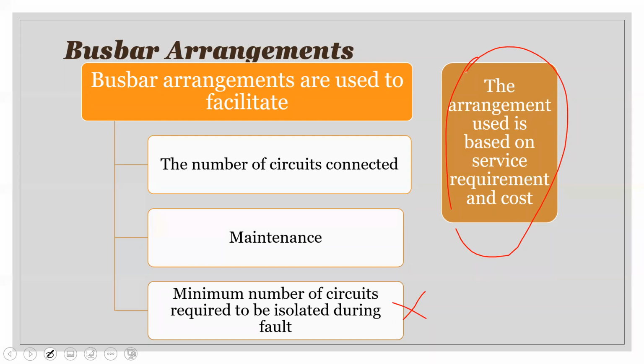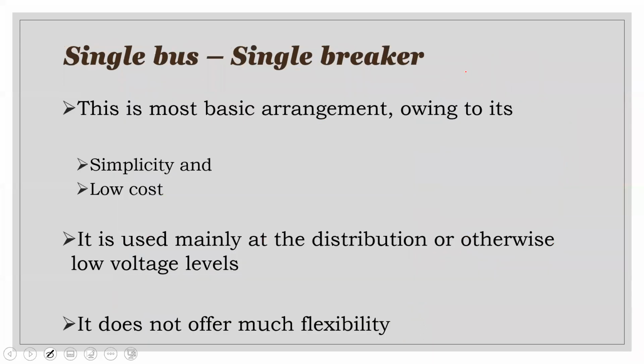All right. The first one I want to talk about is a single breaker, single bus. So one bus bar, and to each circuit, you have a single breaker. Very basic arrangement. It works. It is cheap, and it is simple.